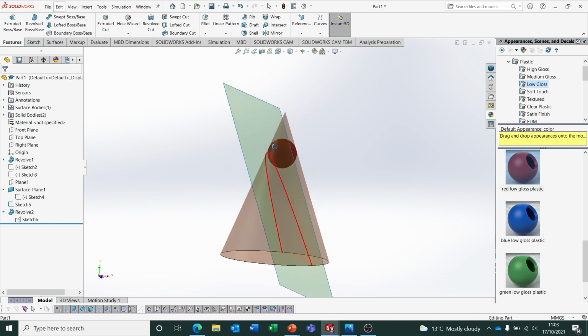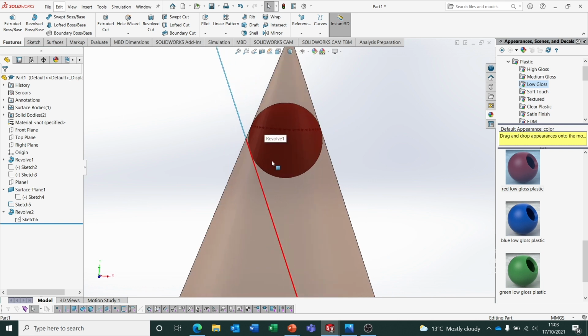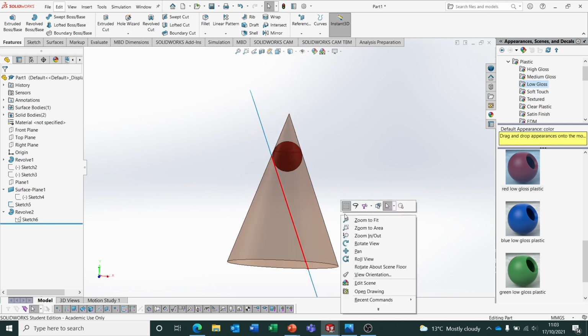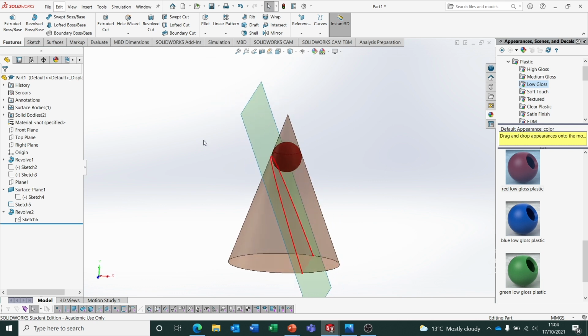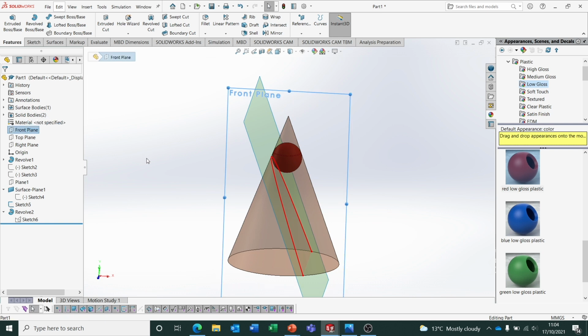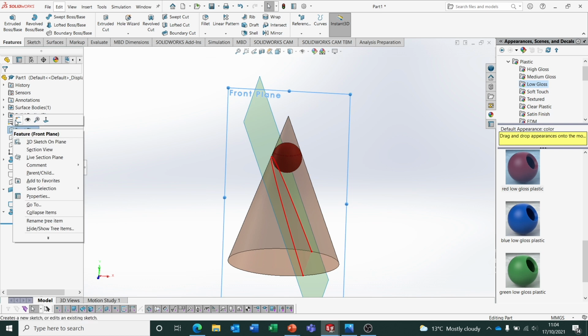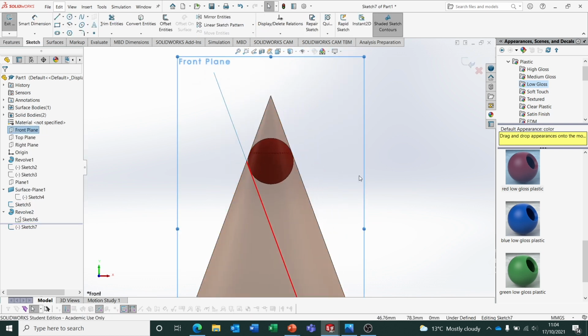All right, so we're going to have to use some kind of basic principles to find that now, our normal and so on. And as well as that, we can find our plane above here, which will give us the directrix. So that plane we used a moment ago, my front plane, which we see this planar surface as an edge view. We're going to use that again, create a new sketch. And we want to find points of contact basically now with that sphere.